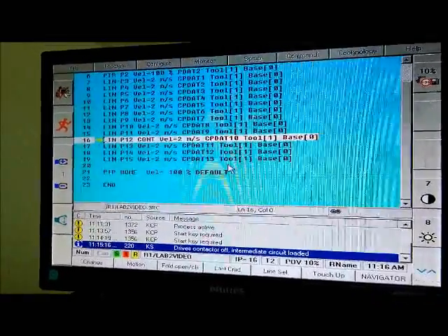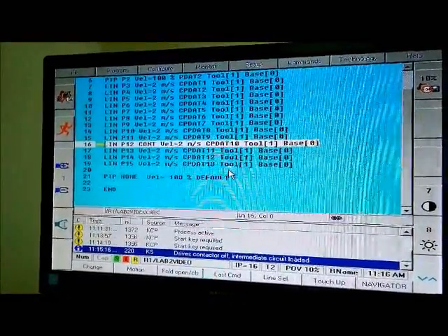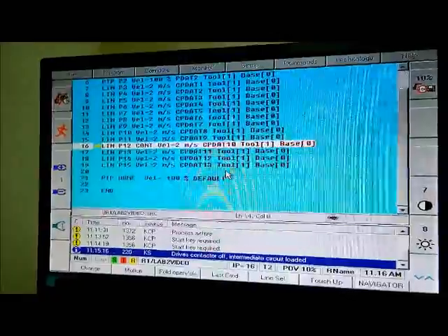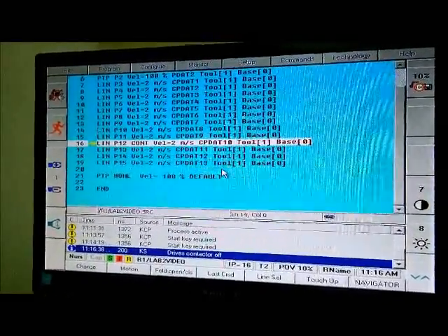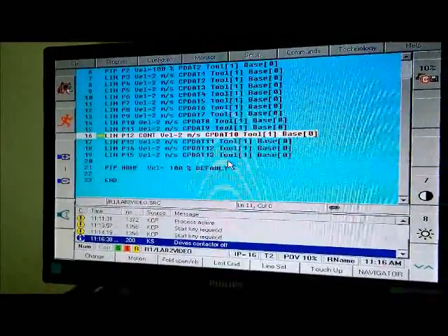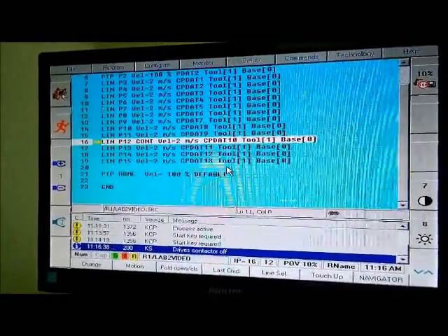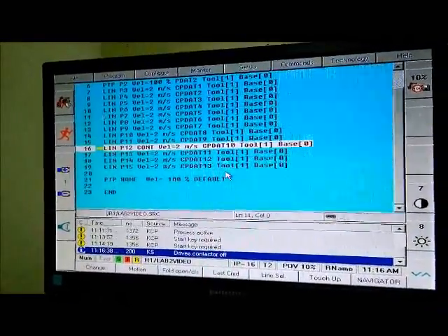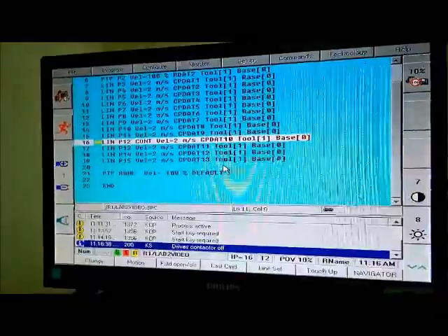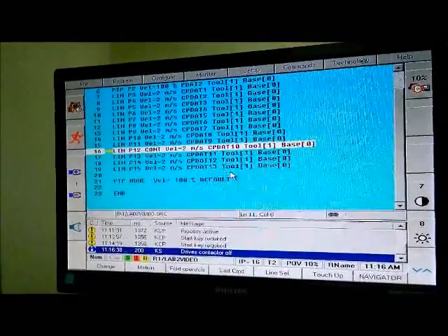So you press enter, and so you have successfully changed point 2 to a continuous movement. Okay. The next command that we want to learn is the wait command. The wait command basically gives you the option to make a short pause according to time. That means how many seconds, time in seconds, before it moves on to the next command.